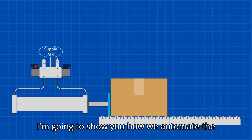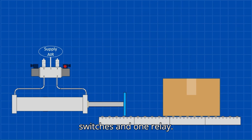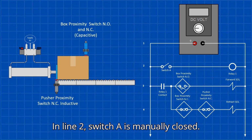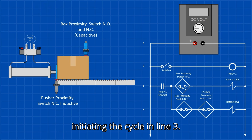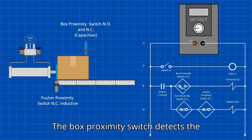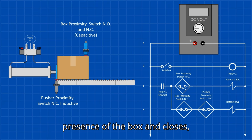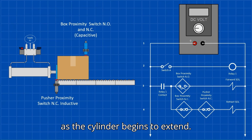I am going to show you how we automate the movement of the cylinder with just 3 switches and 1 relay. This is the ladder diagram for the box pusher. In line 2, switch A is manually closed. Therefore, the relay 1 is energized, initiating the cycle in line 3. The box proximity switch detects the presence of the box and closes, energizing the forward solenoid in line 4 as the cylinder begins to extend.